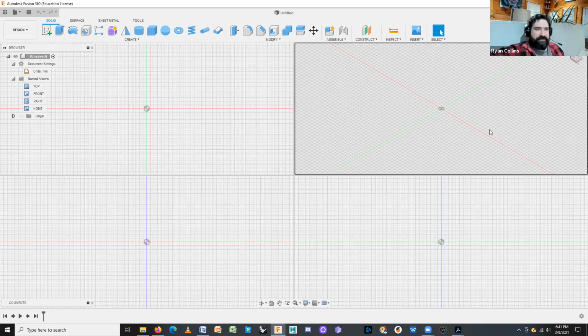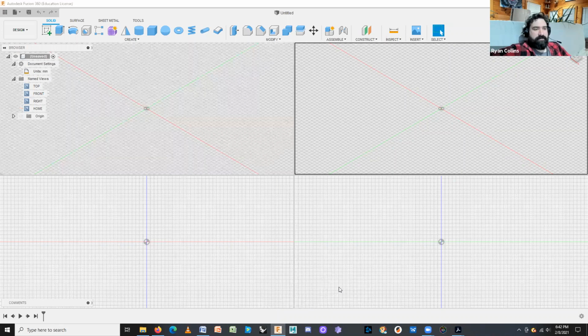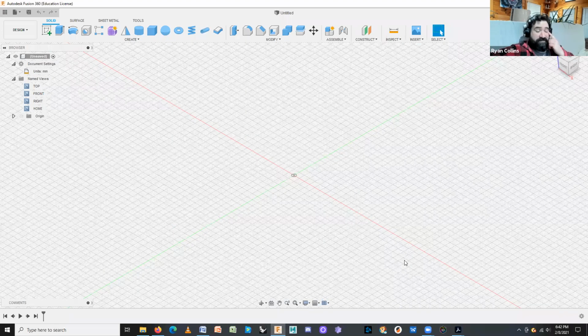So if you're drawing something, this is the more traditional viewpoint or view settings. If you like to work that way, great. I often like to work this way, but sometimes it's more effective, sometimes it's a little bit more confusing. But again, if not, just change back over. Either come down here, go back to single view, or hit Shift I. Goes back to full perspective.